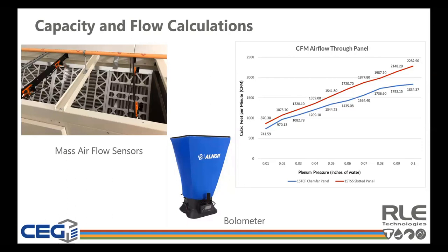Just like with anything, there are factors that affect that plus or minus, right? 156 to 160 assumes you're at sea level, about 65% relative humidity and maybe a 20-degree delta T. You can get your IT load at the rack level via smart power strips, or with the RPP, or with a floor standing PDU, or at the row level using intelligent PDUs, and multiply that total by 156 to get the total number of CFM required for distribution into the cold aisle.